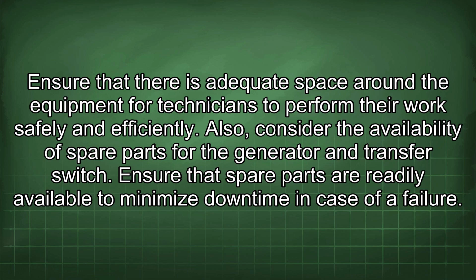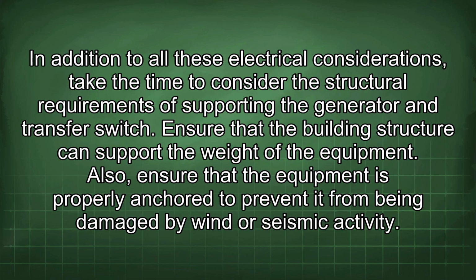Also, consider the availability of spare parts for the generator and transfer switch. Ensure that spare parts are readily available to minimize downtime in case of failure. In addition to all these electrical considerations, take the time to consider the structural requirements of supporting the generator and transfer switch. Ensure that the building structure can support the weight of the equipment. Also, ensure that the equipment is properly anchored to prevent it from being damaged by wind or seismic activity.